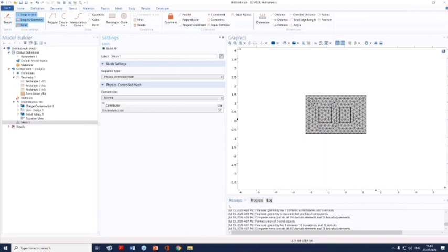How to make a nanocomposite layer, like nanofillers incorporated in a polymeric layer? Well, in geometry, you can create such kinds of geometries wherein you can have one layer, because while creating the geometry, it is not going to say which material you are going to use. It will just be treated as a simple geometric object only. So based upon your design, you can have one solid slab, and inside that you can have some nano pillars, nanofillers, whatever the design requirement is.